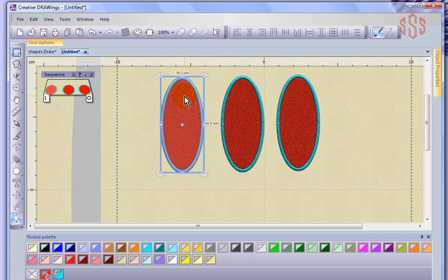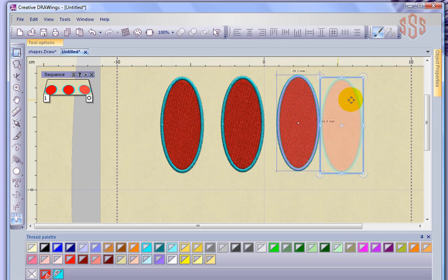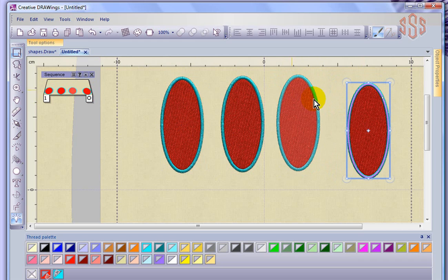So the difference here is I not only duplicate the object in one step, but it also does not get copied to my clipboard, and so you can still have something else on your clipboard and then make duplicates. And when I click and drag and then right click, the new object is automatically inserted where I want it in the design and not simply over top of the first one, which if you're using copy and paste, you need to be careful that you don't put 3 copies of the same object on top of each other and not realize it.